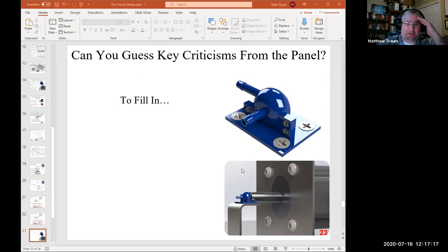So a couple of you guys, and I notice I'm a minute over here, so let me wrap this up in just a second. The last comment that I want to make is to recognize that you guys had asked about manufacturing capabilities and whether this was built or not. We ended up not building this. We didn't select this one and didn't build it. Specifically for that reason, for the concern about how the pump would actually be mounted to the DC motor in a way that eliminated the vibration or the wobble if you happen to mismatch the motor to the pump.